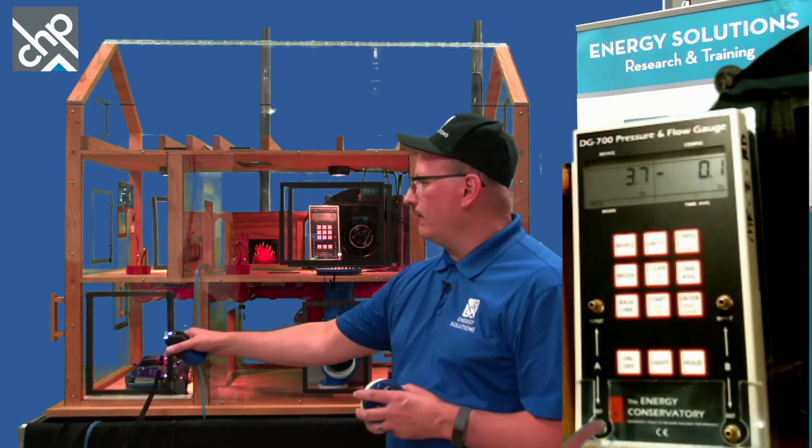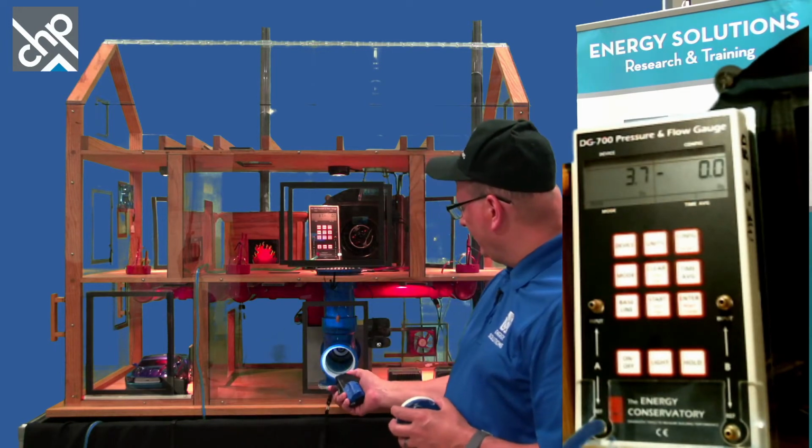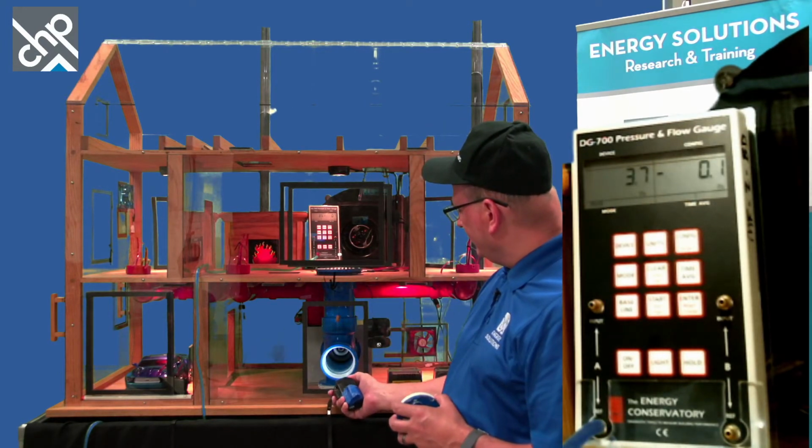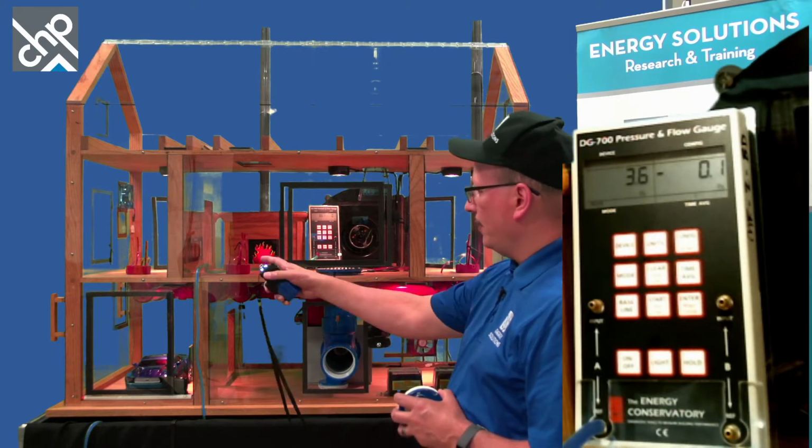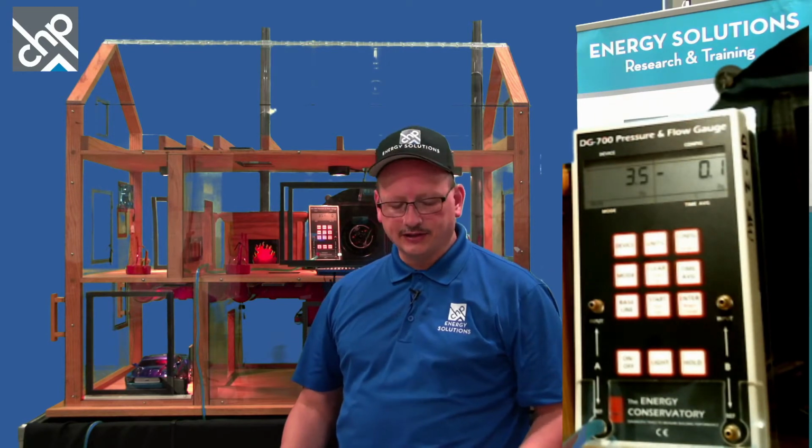If it's in a dirty location, you're also pulling in indoor air quality issues. You might be pulling in fiberglass, dirt. What if this system is in the garage? Would that be a problem? If it's in the garage and you had a return and any kind of leak, that means anything from the garage gets pulled into that leak, goes into the furnace, and then goes right back into the house. So anything that's in the garage is now in the house, if you've got duct leakage in those areas.